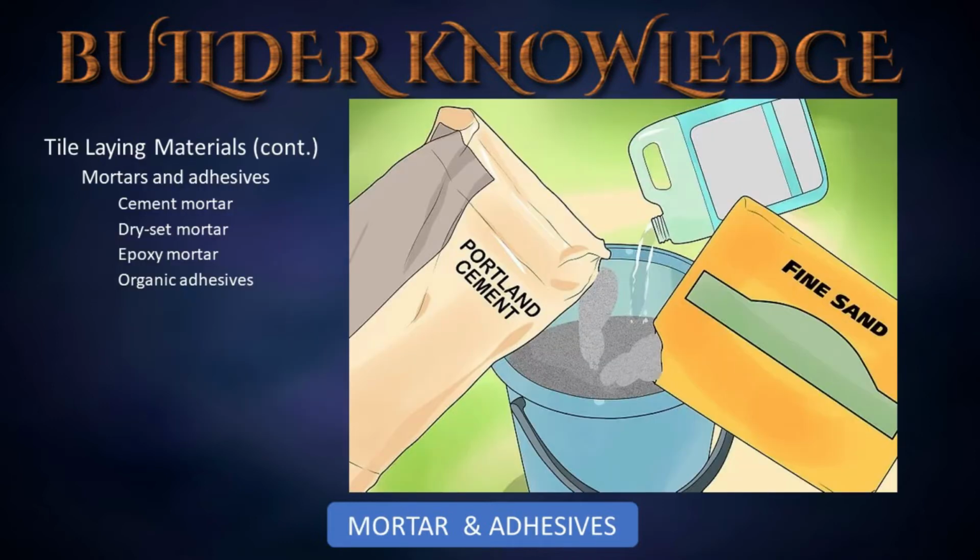Mortars and adhesives. Cement mortar is composed of a mixture of Portland cement and sand. The mix proportions for floors vary from a 1:3 mix to a 1:6 mix by volume. Mix proportions for walls consist of Portland cement, hydrated lime, and sand from 1:13 to 1:15 1/2. Proportions will be dictated by the project specifications.